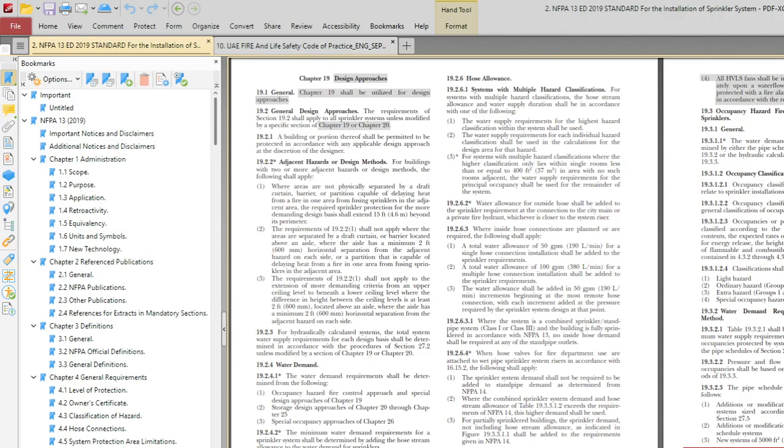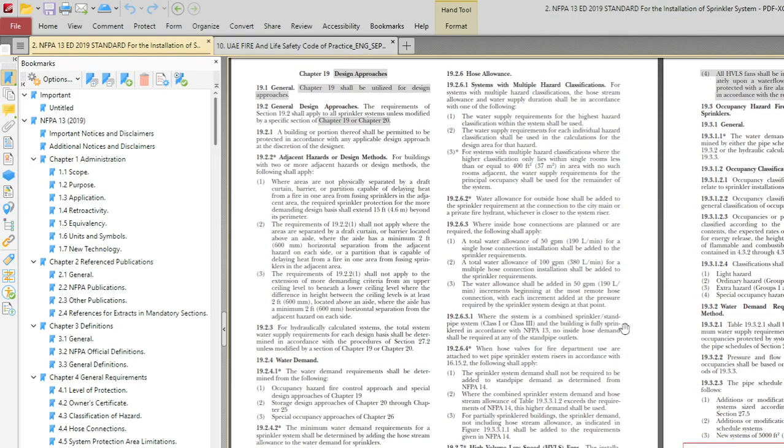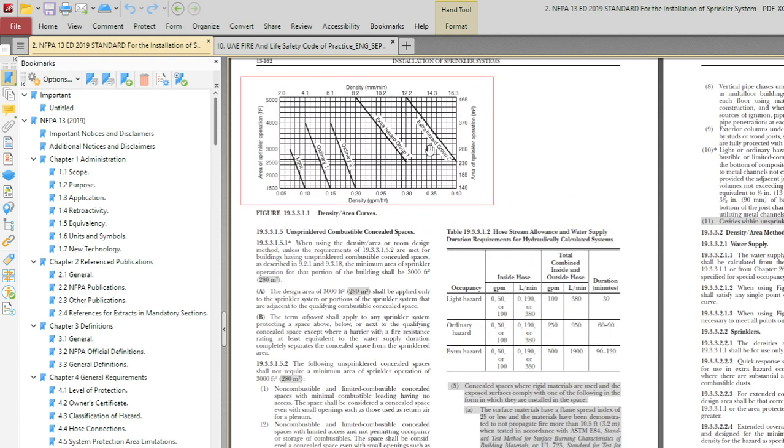So whenever you calculate the pressure rating, you should add residual pressure plus sprinkler head pressure plus piping and fitting pressure, valve pressure, that is designed for your pump head. That means when the sprinkler breaks, the water should flow at this pressure, right? That is the residual pressure. So you can see the reservoir pressure requirement shall be met at the following sprinkler. Now you can see the design density.